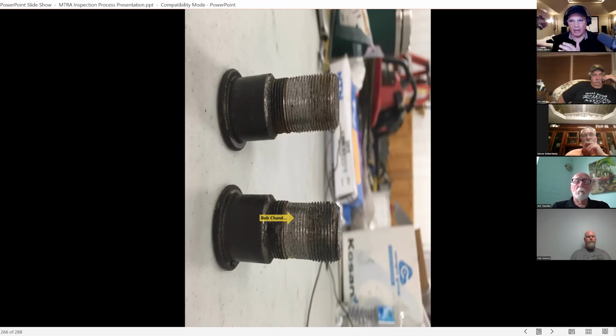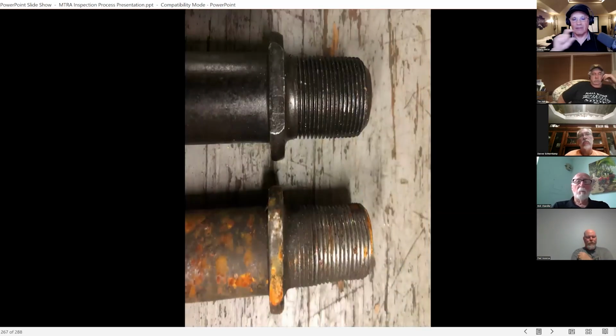Those wheels are hammering on those threads time after time after time. And you see how they're beat down? The threads, little by little, those things are capturing less and less thread, or they have less and less thread engagement. And eventually what happens is the threads strip.